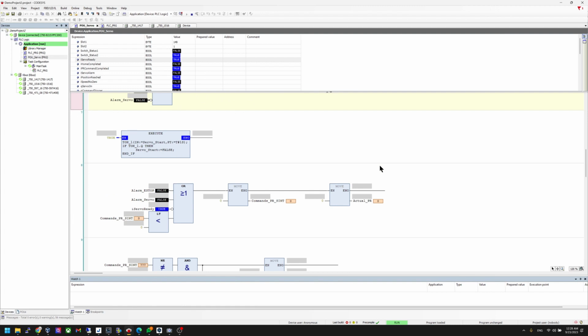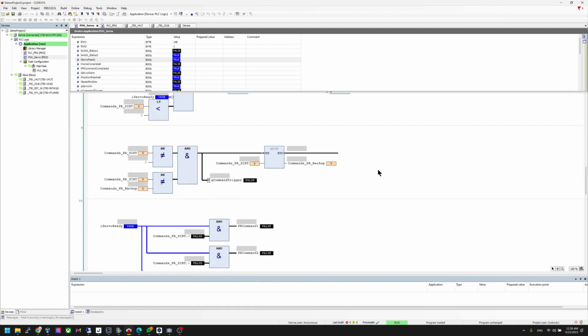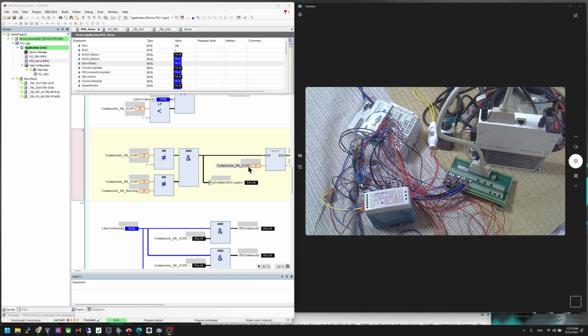Okay. So the next step is I would like to insert some value inside. For example, here, or maybe I need to adjust the camera and my Codesys editor. Okay, now the screen is assigned, looks very good. Then I can turn on the command here. For example, I give a command 3 in here, right click, write all values. Oh, you see the drive is running and turning to position 3.